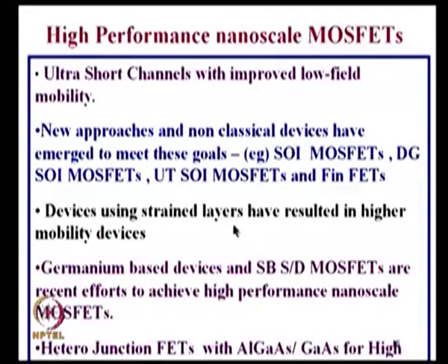So, in n channel MOSFETs, if I can introduce tensile strain, then the electron mobility will increase. So, whatever is good for electrons is bad for holes. Okay. Later on we will again discuss those details.